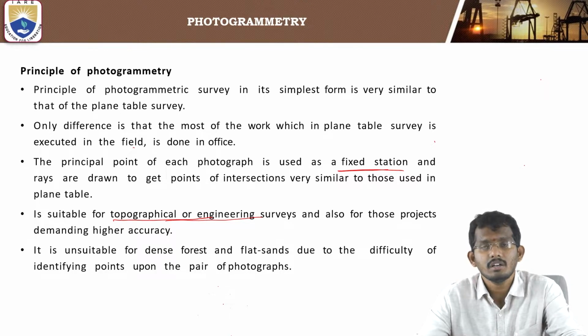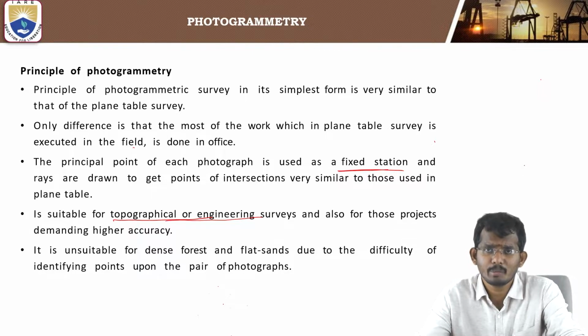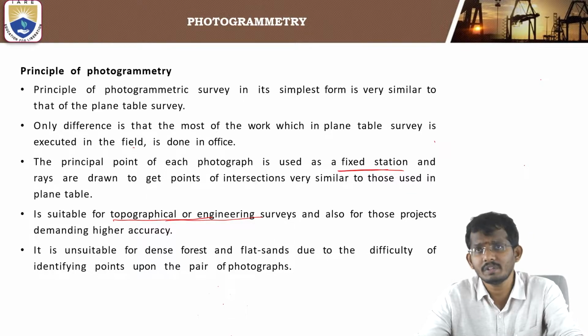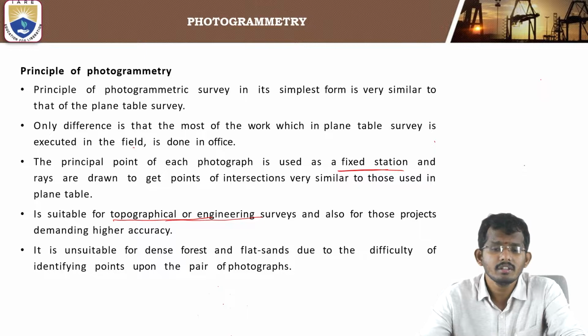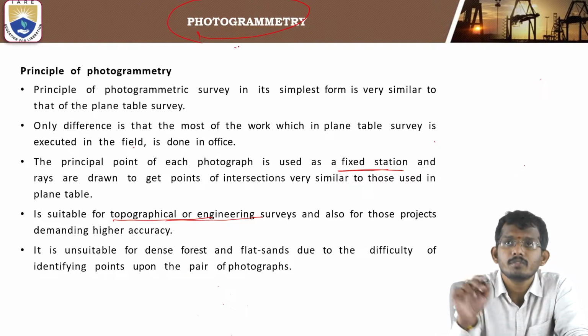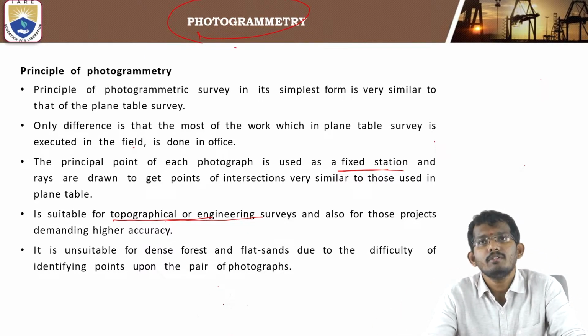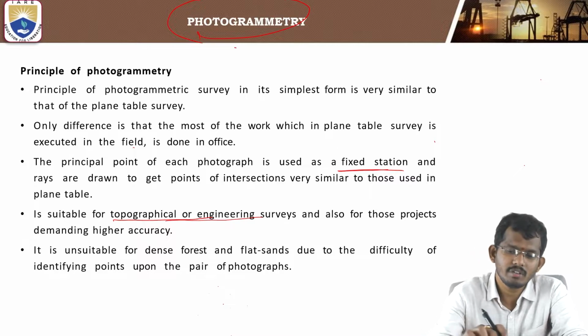So if you want to capture a photo of a dam or reservoir or a very big structure, or any topographic features like mountains, hills, slopes, lakes, plains, plateaus, whatever it is, for those surveys photogrammetry is very preferable. Okay, it is also used for those projects demanding higher accuracy.